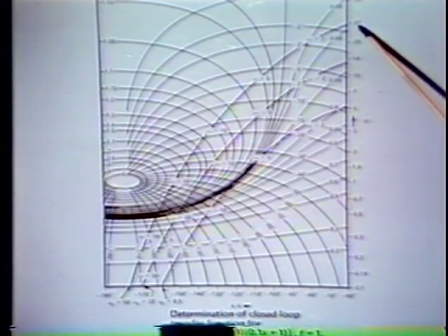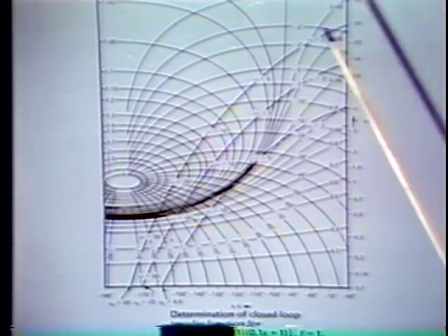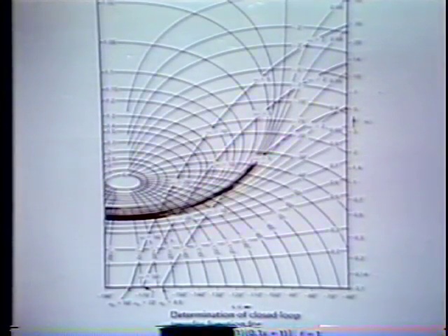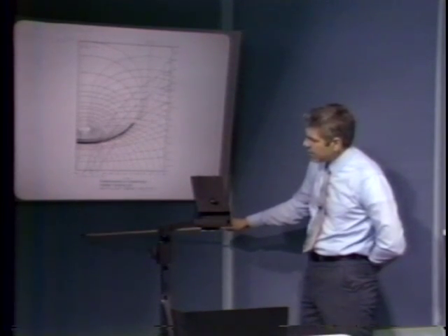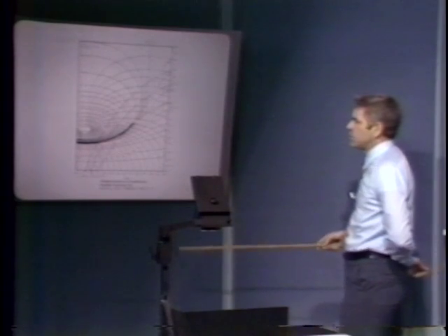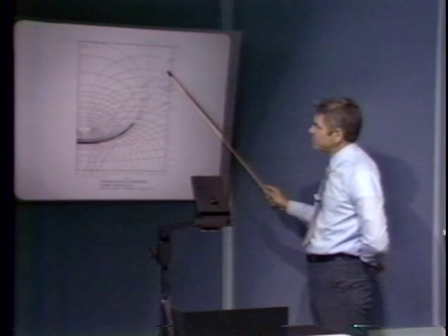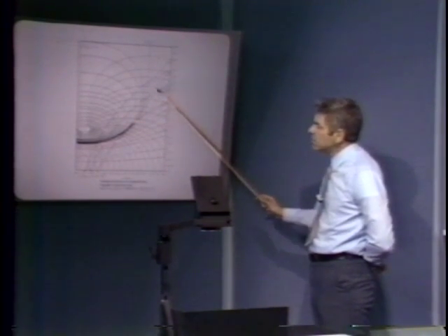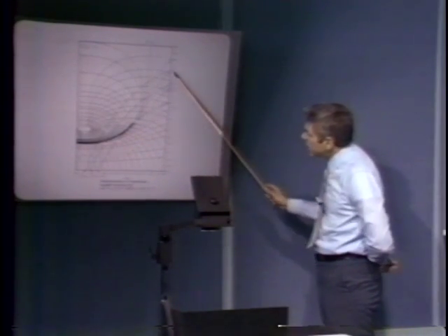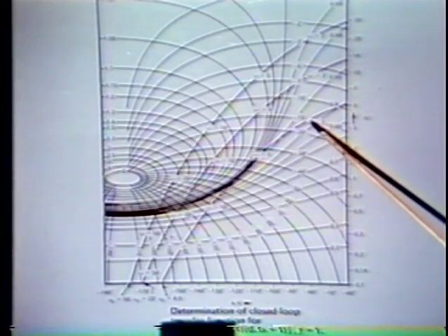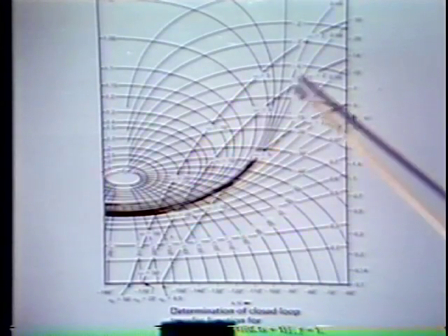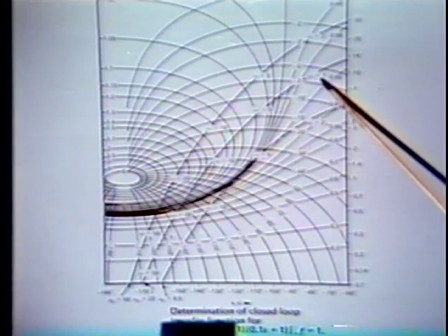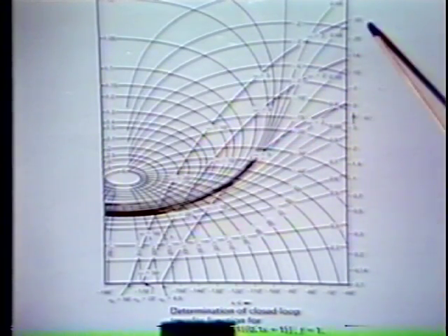These curves, of course, are effectively the left-hand part of the Nyquist construction. If we had the entire gain phase plane running out to 0 degrees here and did our Nyquist construction, we'd have a curve that did something like so, reached minus 180 degrees asymptotically, the contour would close this way and so forth. So what we have is simply the left-hand portion, or a piece of the left-hand portion of the Nyquist construction when we do a gain phase plot of the AF product. Omega is a parameter along these curves. Here we have, for example, on the A0 equals 8.5 curve, omega equals 2, omega equals 5, omega equals 10. Here on the A0 equals 22 curve, omega equals 2, omega equals 5, and so forth. So omega is a parameter along this curve in the gain phase plane.